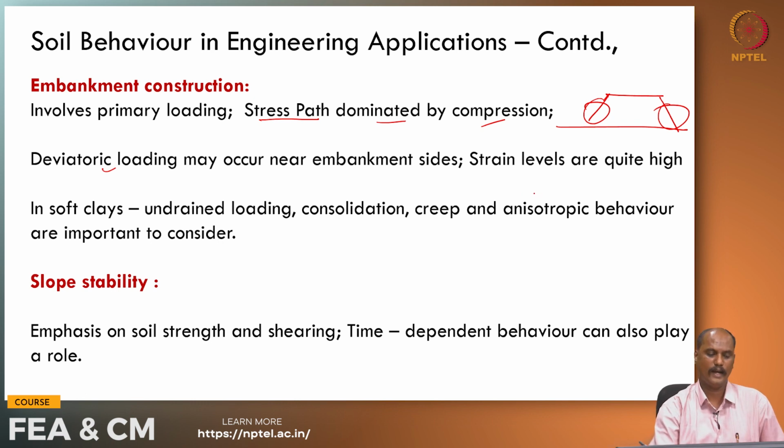The strain levels are quite high, and especially in the case of soft clays, undrained loading, consolidation, creep, and anisotropic behavior are important to consider. We all know what consolidation and creep are, and the anisotropic behavior, especially with respect to soft clays or even peat, is very important to consider in the construction of embankments.